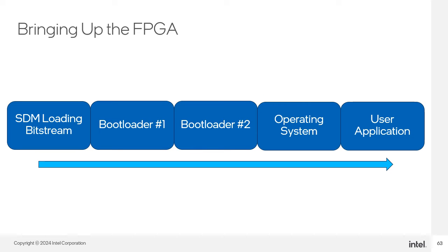The operating system is the third stage boot for the HPS. The second stage bootloader loads the operating system stage into SDRAM. The OS can be Linux, Zephyr, or bare metal. The OS executes from SDRAM. The last boot stage is the application that runs on the OS.